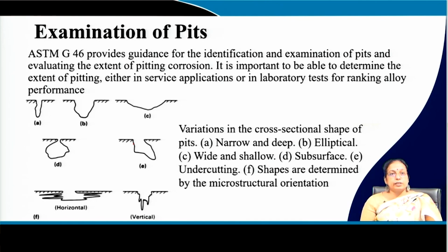That is really a very tedious job, because you have to take at least 1000 or 2000 points per square meter across the surface, and then you have to know this typical pitting volume with the help of an optical profilometer.